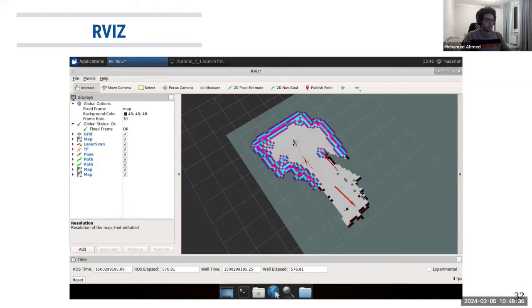So for example, our robot is here. It fired a point cloud. It fired some rays from the lidar. It detected that there is an object here, but these rays can't pass through this object. So it doesn't know anything about what is behind this object, so it drew these gray cells. It doesn't know if it can go here or not. But maybe when it moves through these free cells and comes here, it will see what is there. So we can update the map and continue navigation.